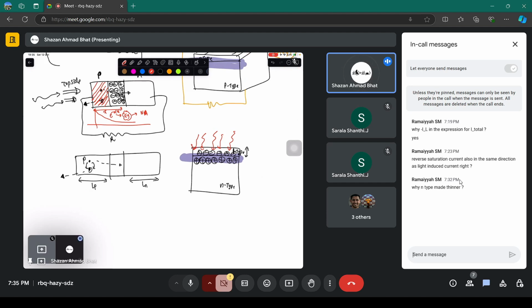We will be successful if this p layer is of the order of a few nanometers or maybe a few micrometers, so that light can at least enter. Whenever the light enters this region, it exponentially decays, e to the power minus alpha times z, where this coordinate is z here.